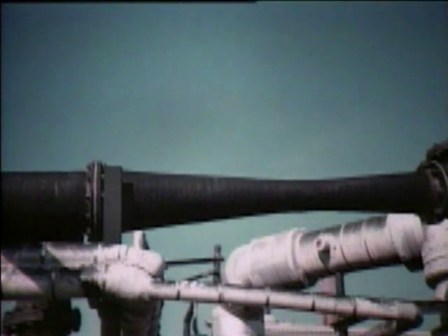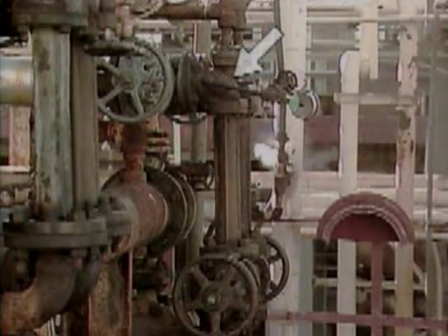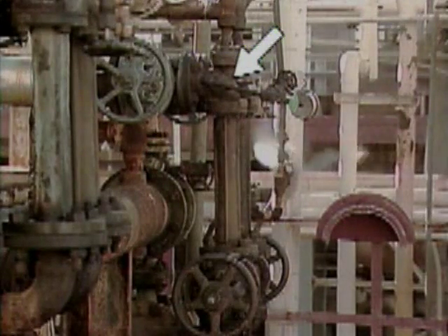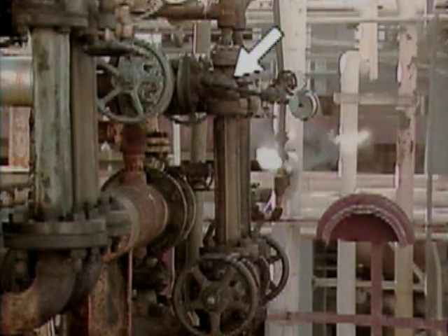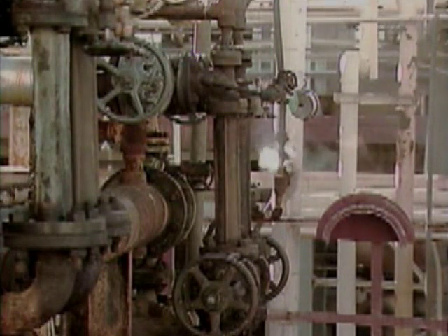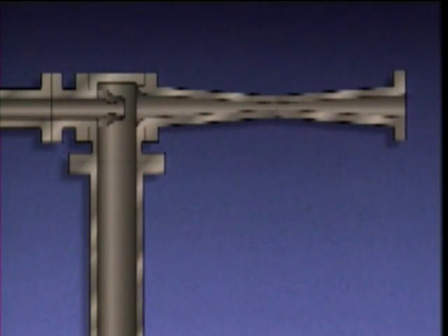Another component that's used in liquid as well as gas and vapor systems is a jet pump. A jet pump uses the flow of one fluid to move another fluid. An ejector that uses steam to remove air and other non-condensable gases from a condenser is one type of jet pump. There are no moving parts inside a jet pump. Instead, the pump relies on energy conversions to operate.